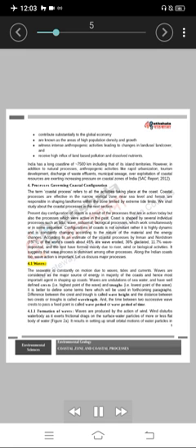4.1 Waves. The seawater is constantly in motion due to waves, tides and currents. Waves are considered as the major source of energy in majority of the coasts and hence most important agent in shaping up coasts. Waves are undulations of seawater, and have well-defined crests, i.e. highest point of the wave, and troughs, i.e. lowest point of the wave. It is better to define some terms here which will be used in forthcoming paragraphs. Difference between the crest and trough is called wave height and the distance between two crests or troughs is called wavelength. And, the time for two successive wave crests to pass a fixed point is called wave period.